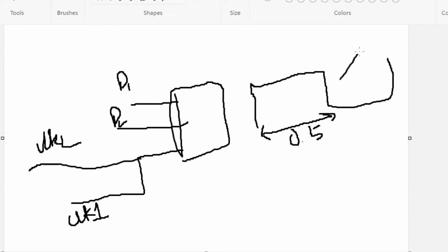So the min pulse width should be a minimum of 0.5. This is the rise pulse width, right? So my min pulse width should be greater than or equal to 0.5. If it is less than that, we will get frequency errors, like performance issues, so it is not meeting the frequency. We can say these are timing issues. This may lead to setup time and hold time issues also. We need to take care of min pulse width variations.